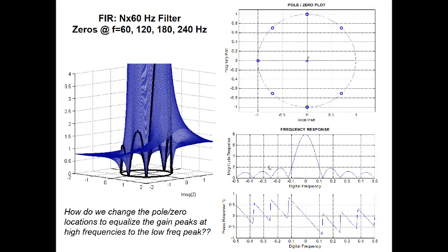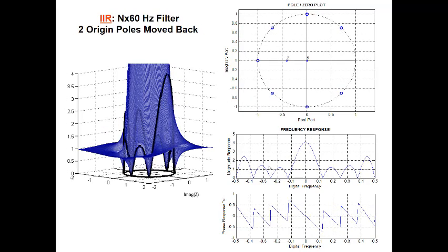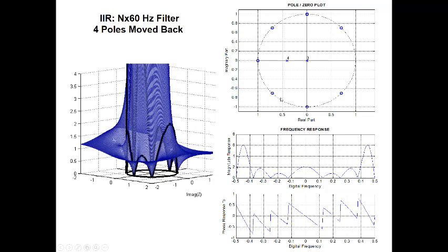And now after we're kind of going in the right direction, we're giving a bit too much emphasis over here to this one, this notch here at the Nyquist rate caused by this. So we're getting kind of close to this part of the unit circle, causing that to be boosted more than we are over here between some of these other ones. So we might start thinking about, well, let me move these poles off the real axis and kind of move them a little bit closer to some of these ranges that need more boost. And maybe let's bring some more back too.